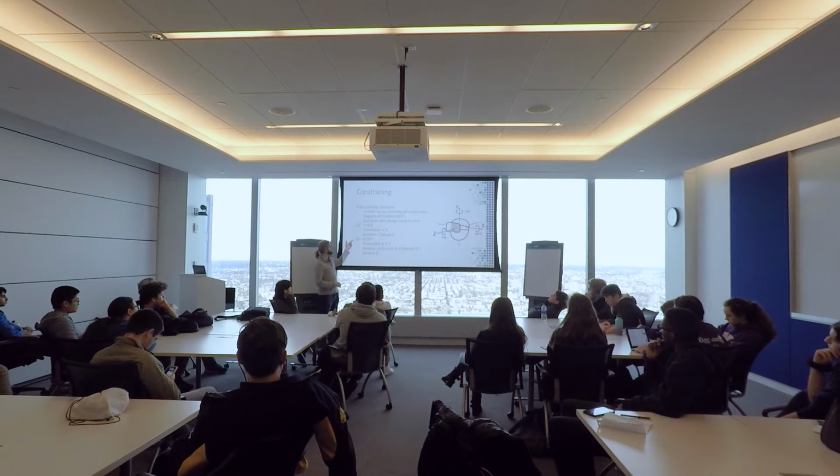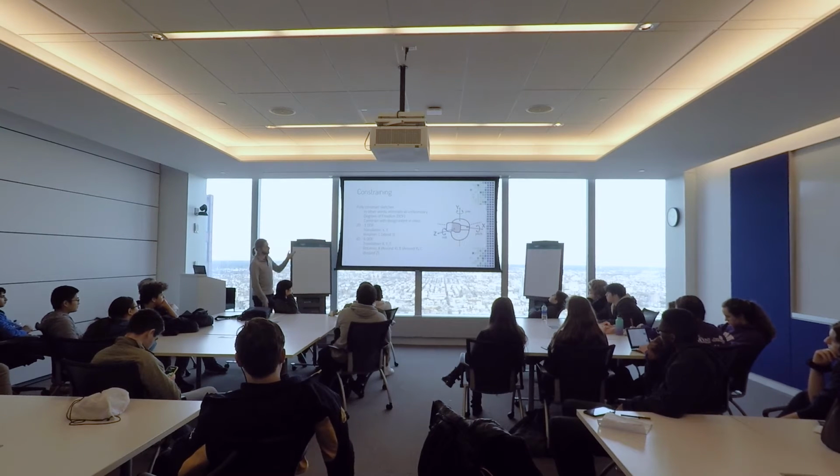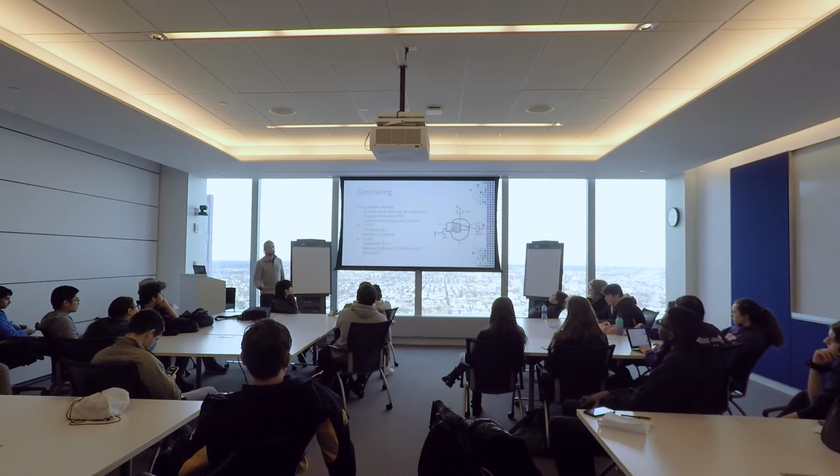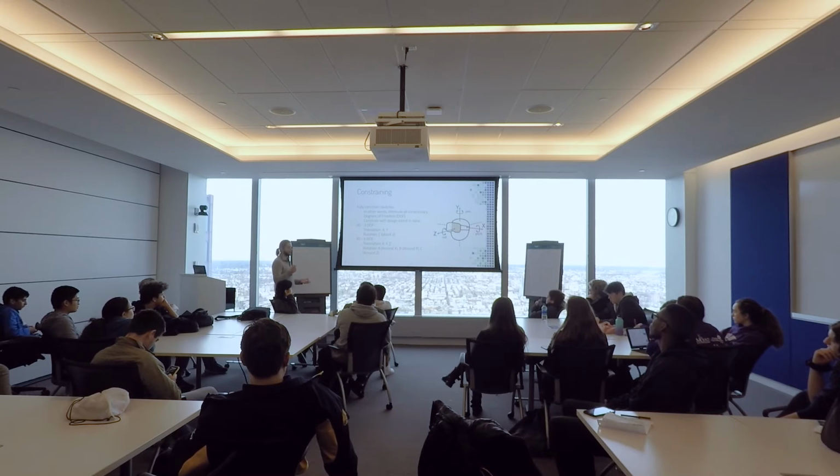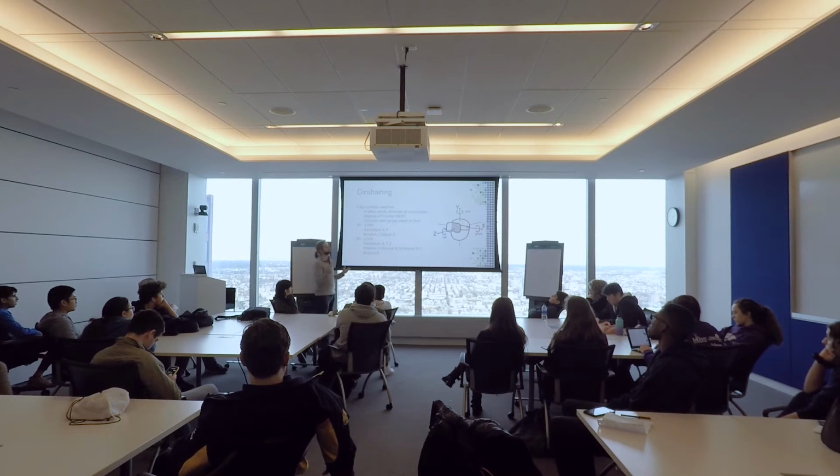3 dimensions are 6 degrees of freedom. You add in the Z, and then you also add in the B axis and the C axis, respectively. So it gets exponentially more complicated with adding another dimension. And the goal when you're constraining things is to eliminate all those degrees of freedom. Both SolidWorks and Onshape and all other CAD programs have visual ways of representing fully constrained things.